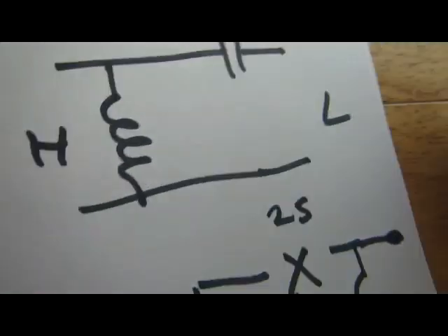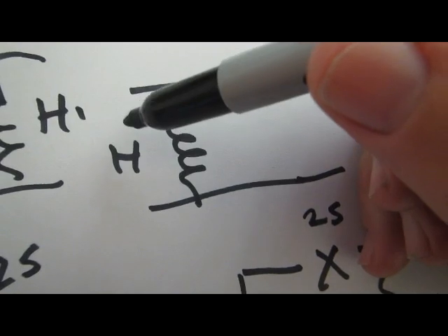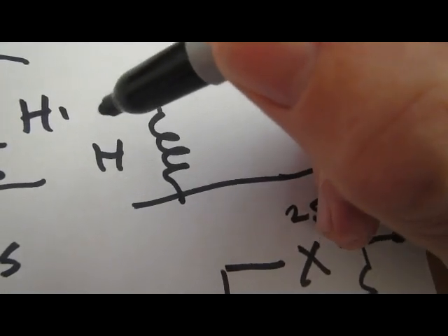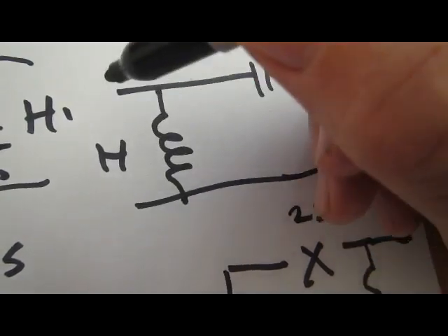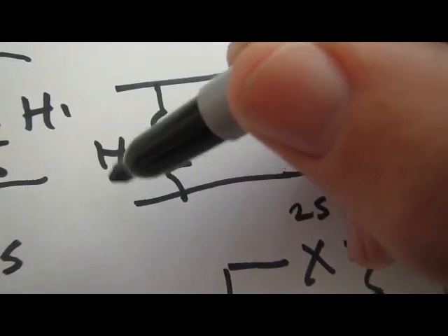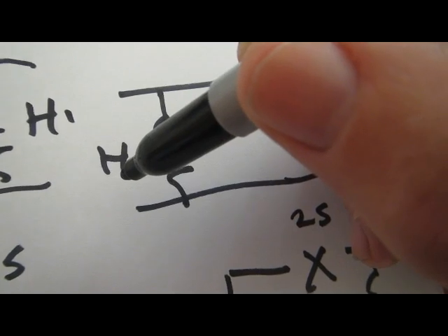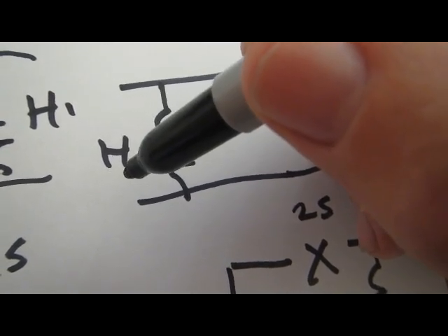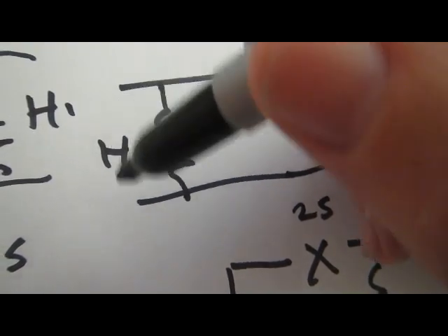In the parallel case, if I've got a very high resistance here, matching high to low, if that's got some series reactance, then for the load alone I must express the reactance as a parallel element in the way that I've showed you previously with capacitors.